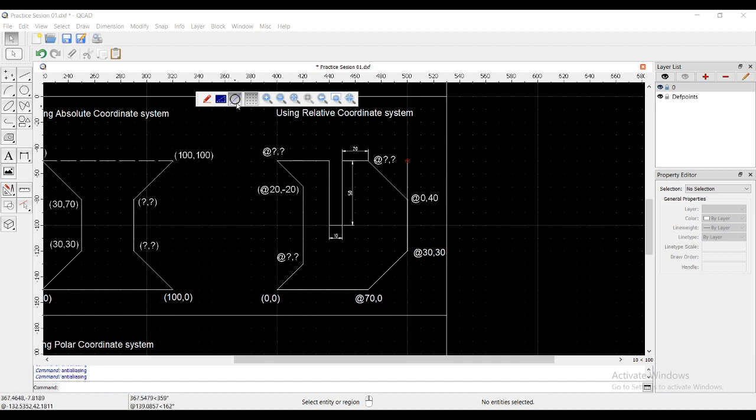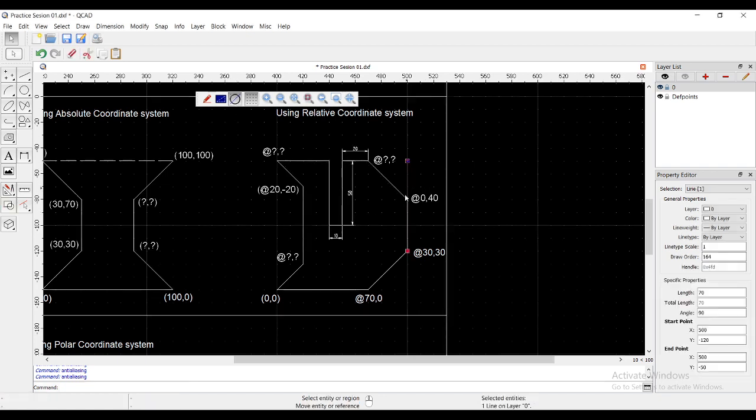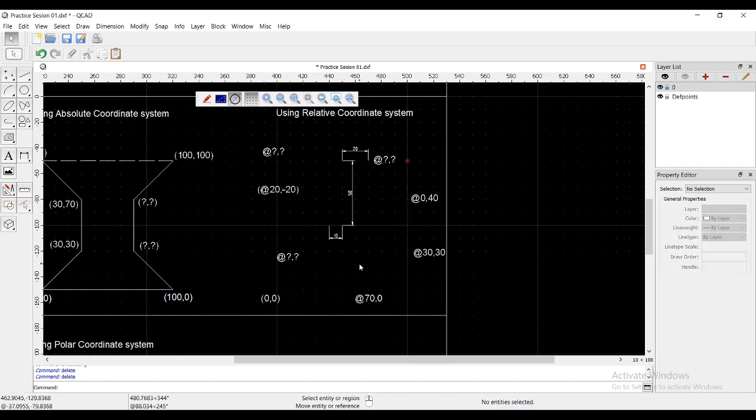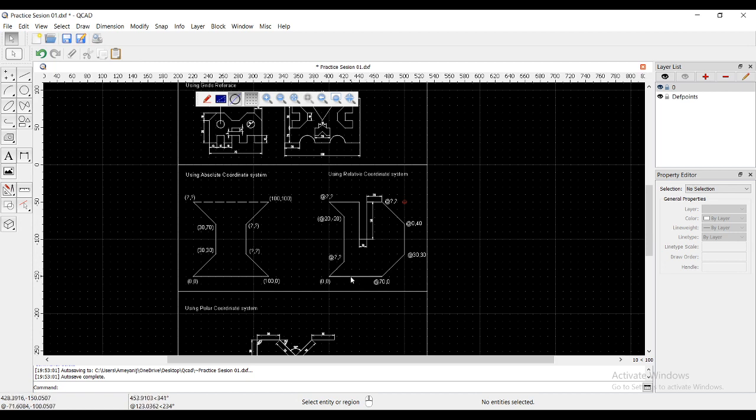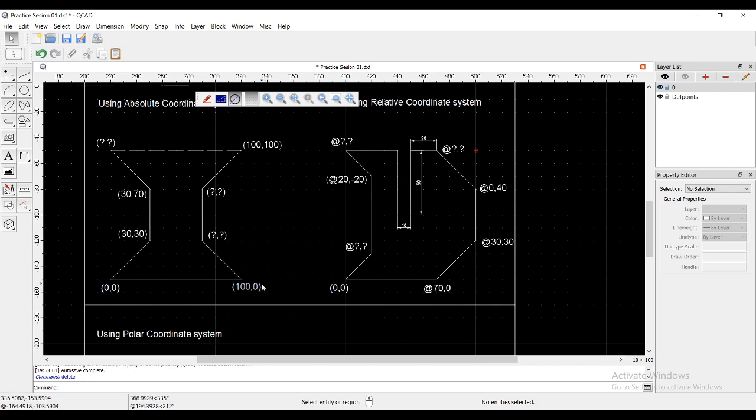So if I switch on the anti-aliasing, everything which is in the first layer gets transparent and you get these darker lines. So it is very easy to select those darker lines and delete, so that those lines you can see there. Here I have a larger thickness, here it is a smaller thickness, so this is a single line, this is a double line, so I can just select and delete it. So it is very easy to find the overlapping lines, which is anti-aliasing. So that is the effect which you can use to find the overlapping lines.